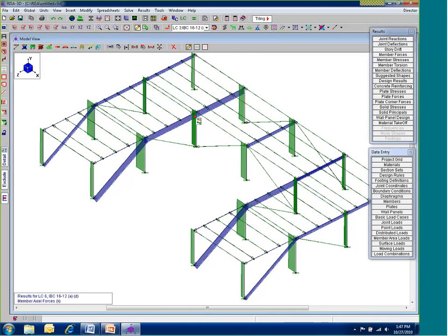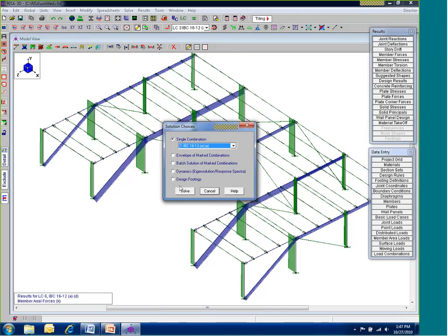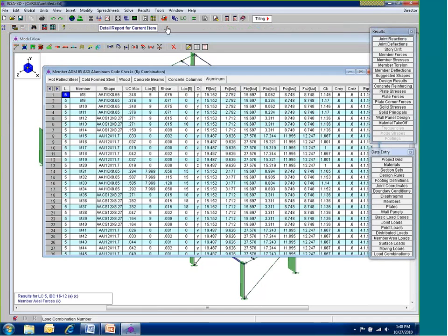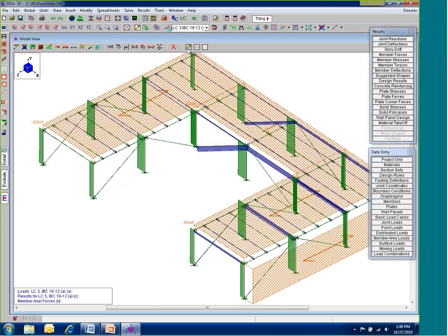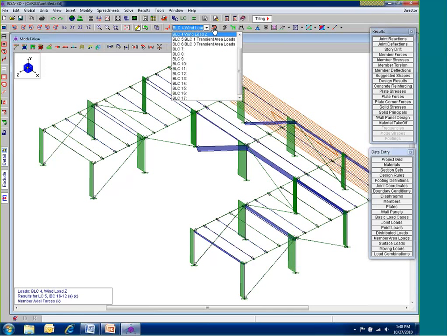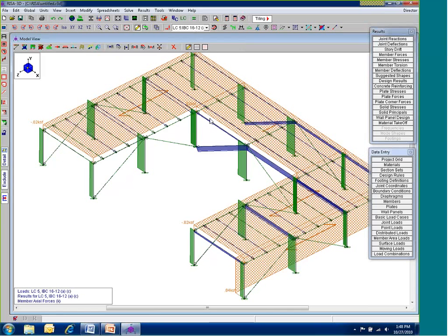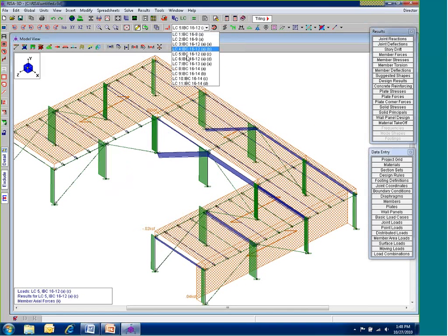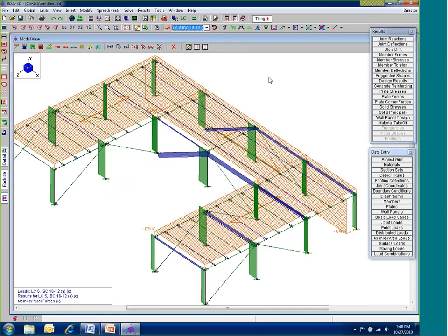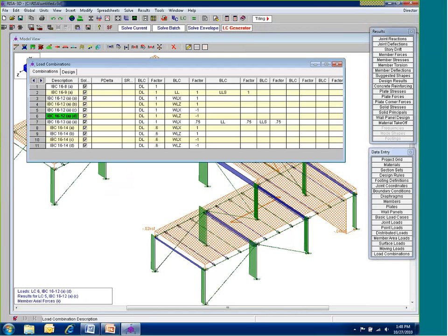Now, if we run the loads in the other direction, we're going to see that load combination 5 is going to be solving it, running the loads in the opposite direction. I'm going to display that for you so you can see that. Blowing wind in load combination 5, which I think is the right one we want to be looking at. We need 7, I think, which is going to be reversed there. Okay, so 6 and 5 are the ones we were worried about.